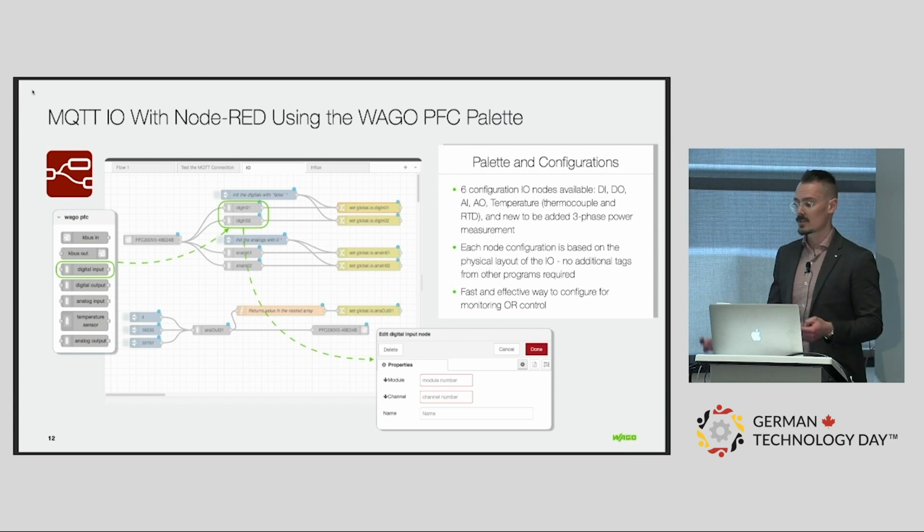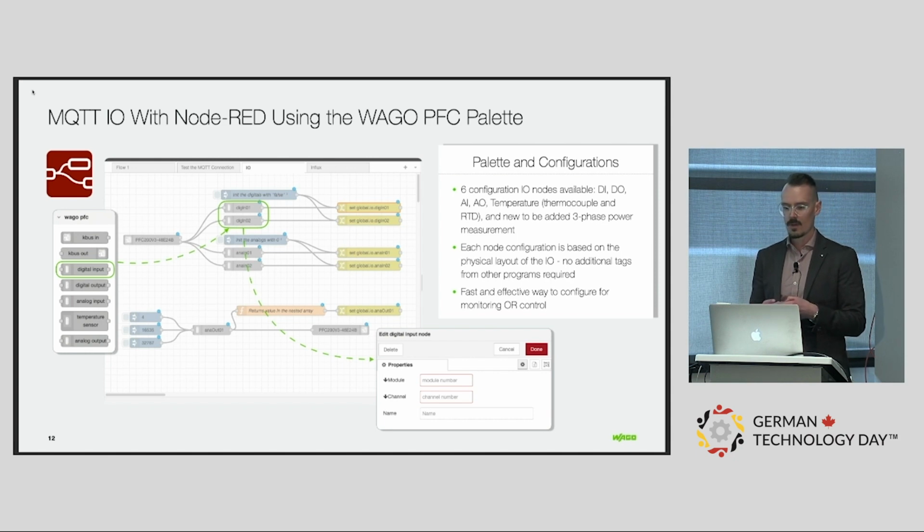One of the things we want to talk about is that we actually have enabled you to download this software package, the MQTT K-Bus API is what we call it, and it allows you to interface with all the I/O points on board the I/O system via MQTT. So you can install what's called an MQTT broker right on the device, and you can interface between software and the physical I/O points on the device via MQTT.